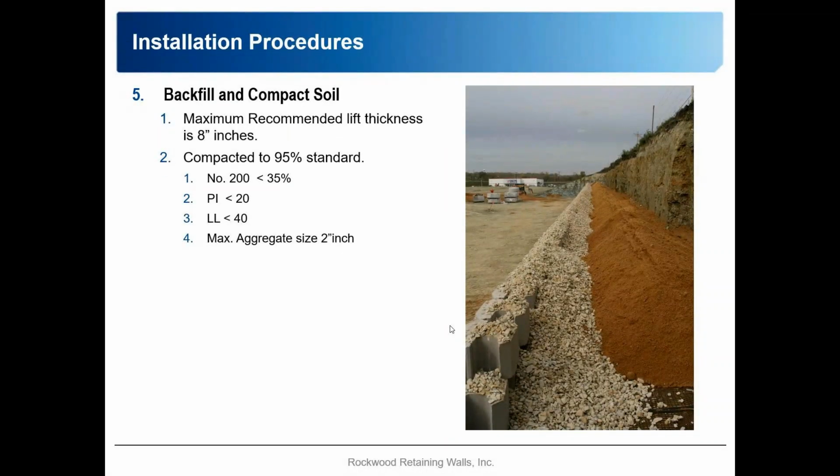Here's an example of it being placed. So you can see the drain rock area about 1 foot, and then the backfill material. In this case, the contractor is using kind of an import backfill material. You can see the on-site cut right here is more of a clay or a silty material. This is certainly not the same material that they've excavated out. This is coming from a quarry or a pit.